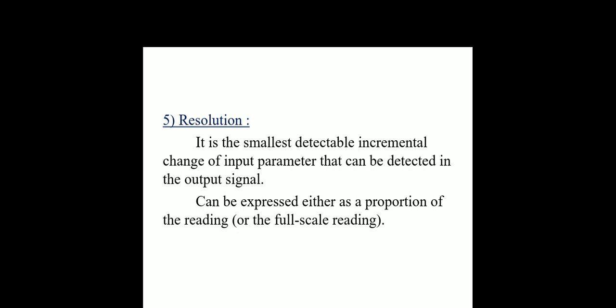Next is resolution. It is the smallest possible change at the output. It can be defined as the smallest detectable incremental change of the input that can be seen at the output signal. It can be expressed as a proportion of the reading, that is, the full scale reading.